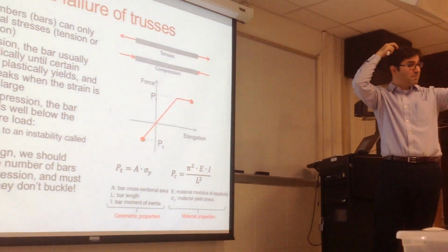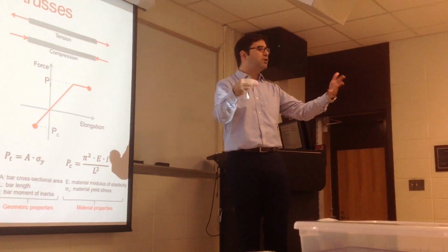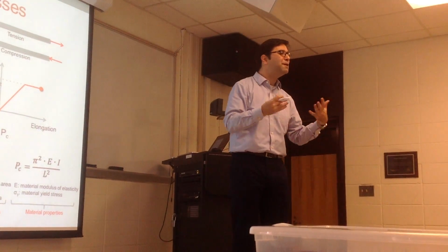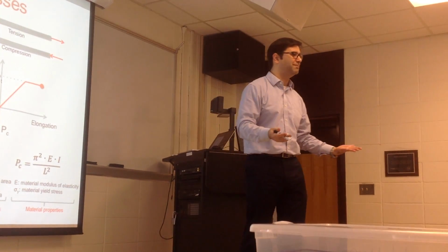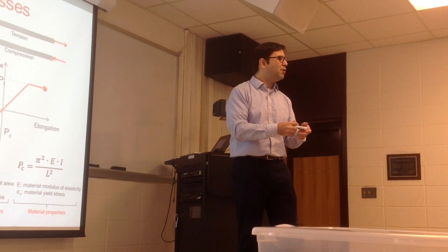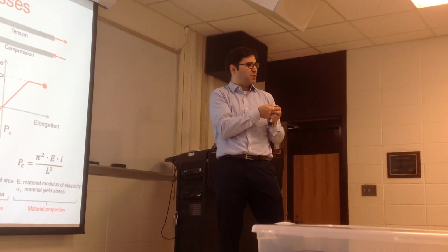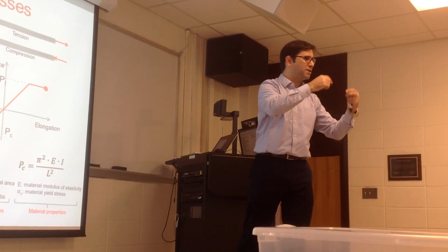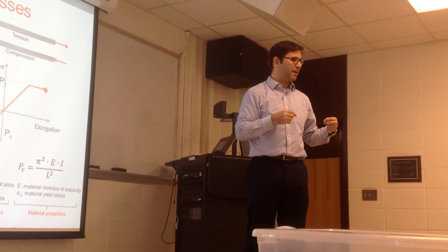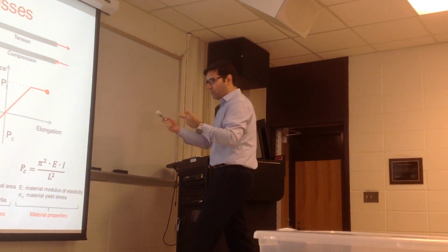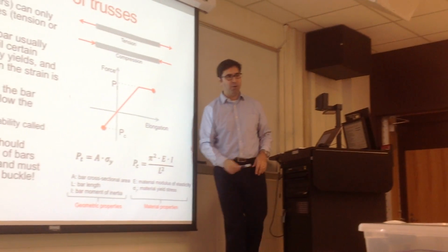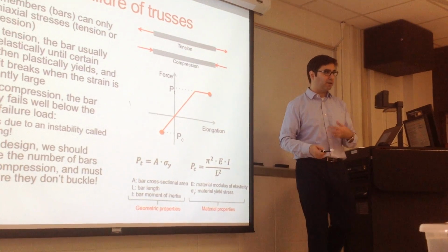Yes? It will buckle. So I always go to the extreme case. You know, a very slender bar is a cable. You can pull a cable as much as you want, but the moment you push at the ends, it just goes out. And there is a formula to tell you how much load a cable or a bar can take under compression.